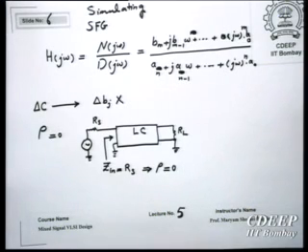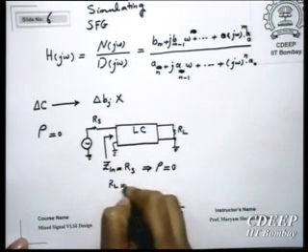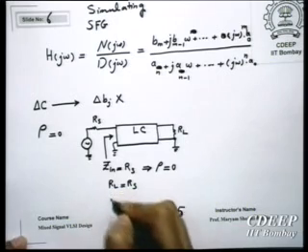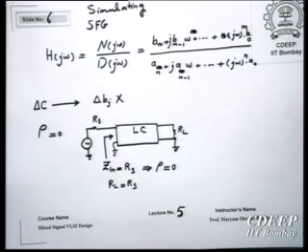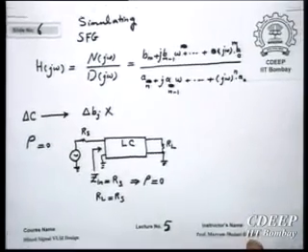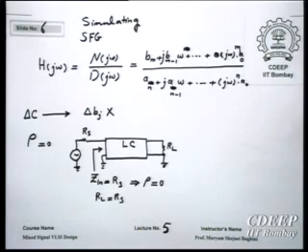In this particular case, and of course RL equal to RS, it can be shown that actually the amount of variation will be very small. And that is the reason these filters are always used in a maximum power transfer mode, meaning when the reflection coefficient is 0, because they actually can mimic a very robust filter with respect to variation.